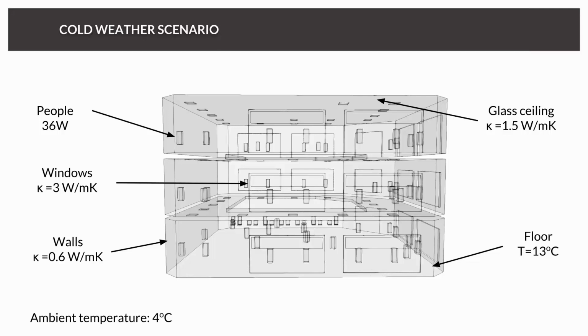Okay, Paul described what his question was about when you talked about natural ventilation. Well, it depends, Paul. If you have an opening at the bottom or the top of your building, then you need to put an outlet there. But usually, and that's a big difference, the openings in your building are not modeled as outlets in a natural ventilation simulation. The outlet boundary condition is only used for the ambient.